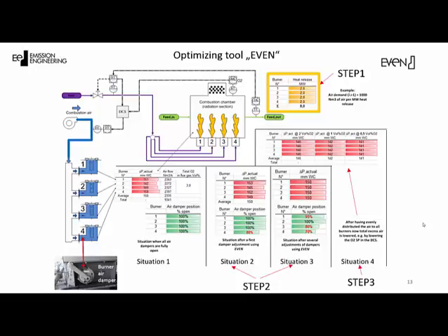In practice, Step 1 would therefore consist of checking the fuel gas pressure upstream of the burners. If the pressure is the same on all the burners, then the heat release will also be the same. If no pressure gauges are available, it is a reasonable assumption that the fuel gas will distribute evenly among the burners as long as they operate at a decent fuel gas pressure, for example with more than one bar gauge, and the gas tips are in adequate conditions. Step 1 is herewith finished.